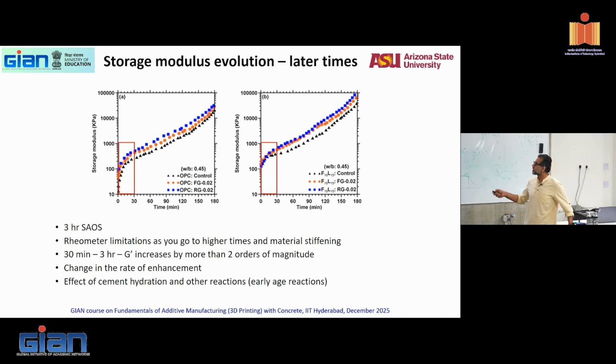You get storage modulus as a function of time. And you can see here that from 30 minutes to 3 hours, your storage modulus increases by more than 2 orders of magnitude. Very quick structuration rate, right? Which means how much you can carry at 30 minutes versus how much you can carry at 3 hours is much higher.